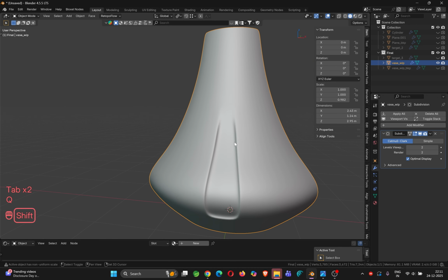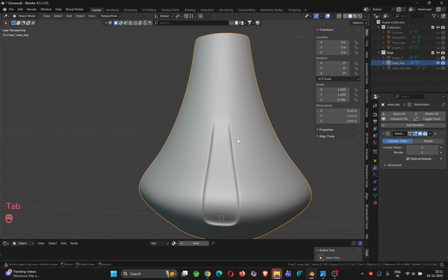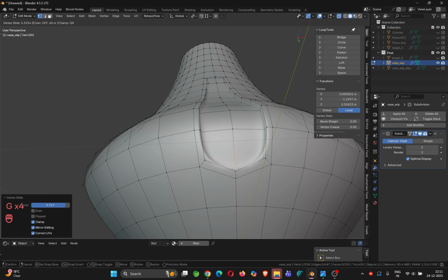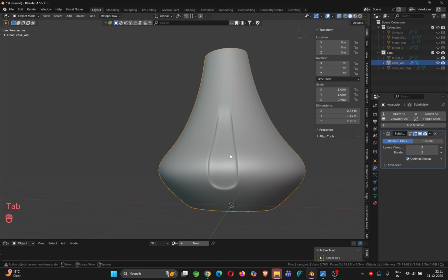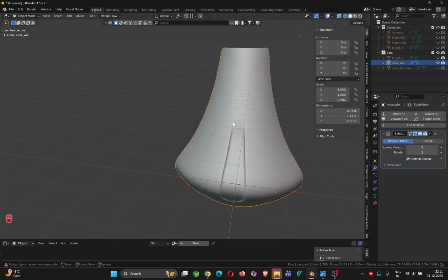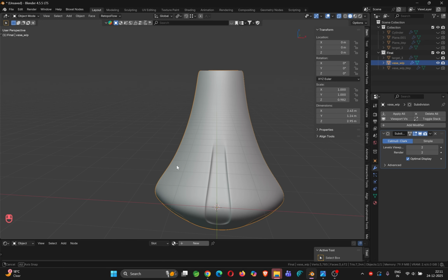Maybe move it this side a bit, this side a bit. Yeah, looks fine to my taste. Or maybe you can just move this a little bit down here, this also down here, so that I have a nice rounded shape like this. You see, looks good, right? Now, be careful: whenever you apply subdivision on such a segment of base mesh, it will round the corners. Now if you try to apply a radial array on it, it will not allow these edges to merge properly.